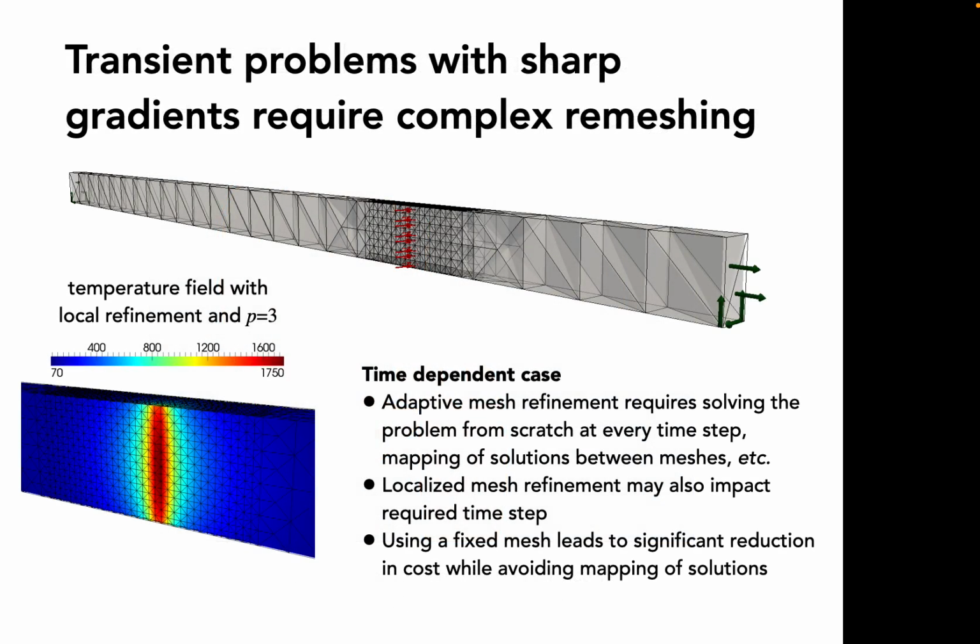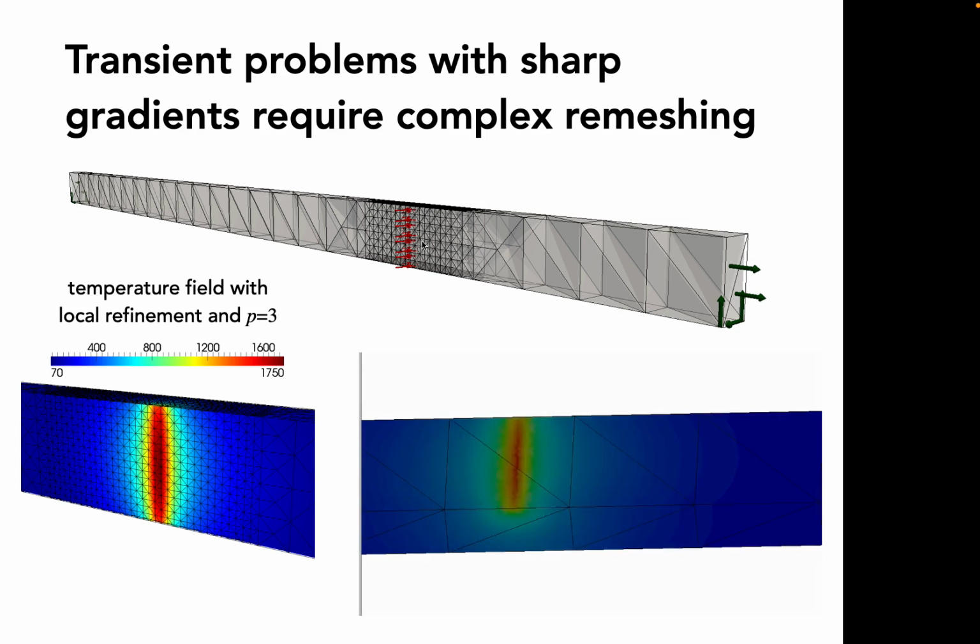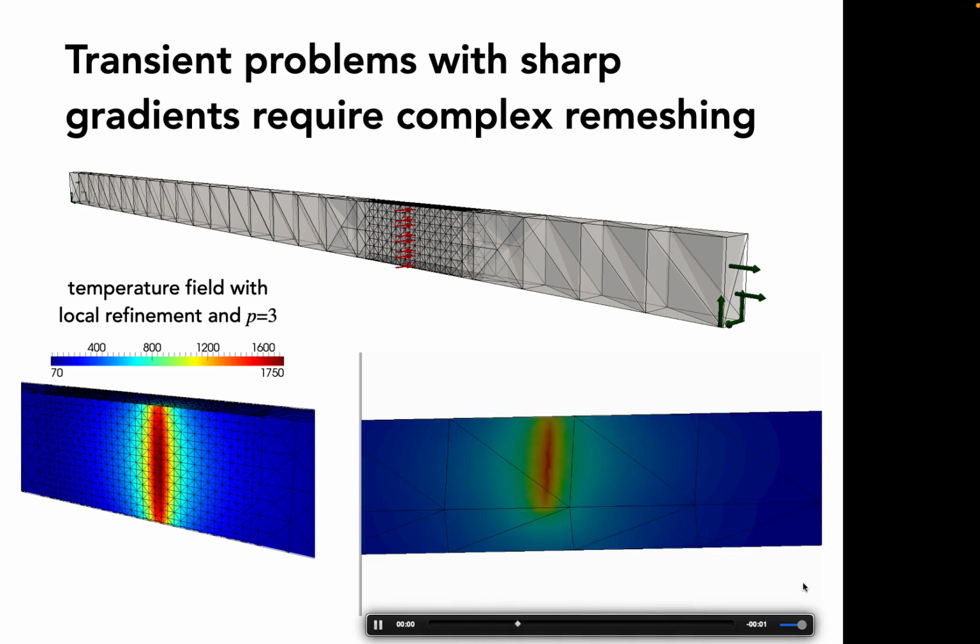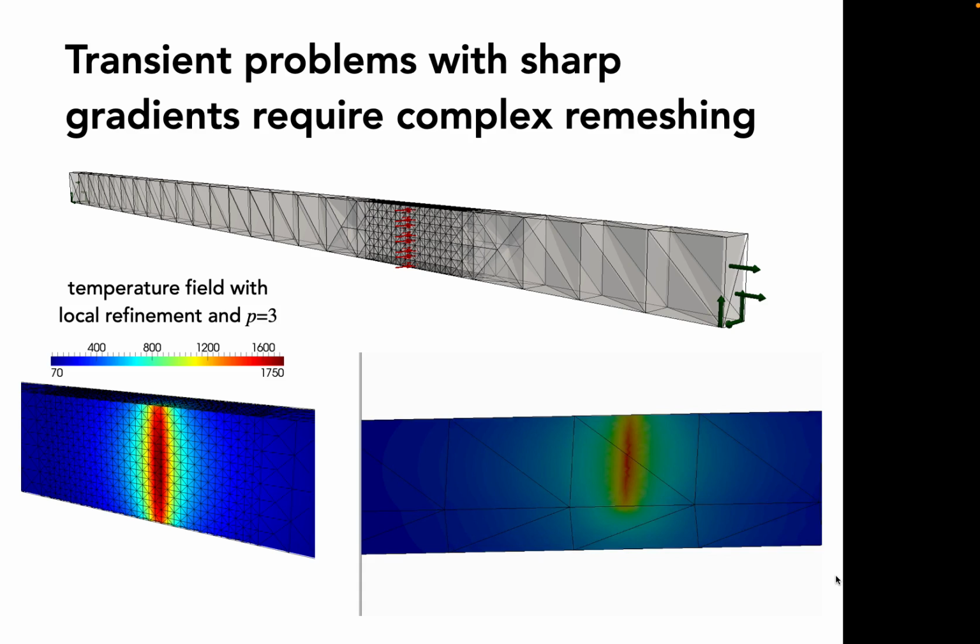And then, we talked a little bit about sharp gradients. If you want to capture this localized heat load, then you need to refine the mesh. Otherwise, you don't capture the sharp gradients. But if you can also enrich with a function that can do that, then you see that with a very coarse finite element discretization, you manage to capture that, and that is because again we are enriching the approximation space with functions that can actually reproduce this behavior.